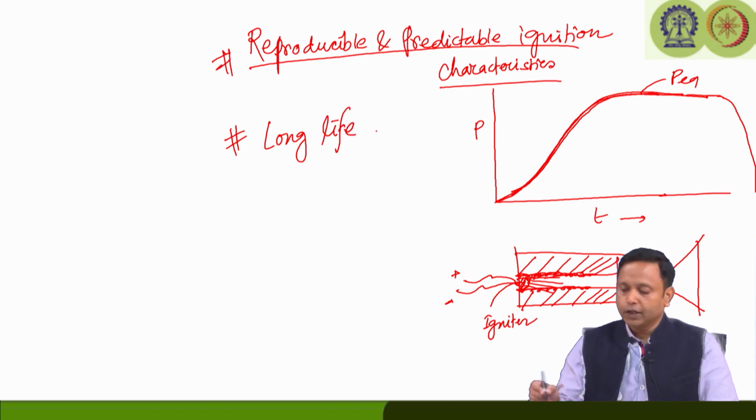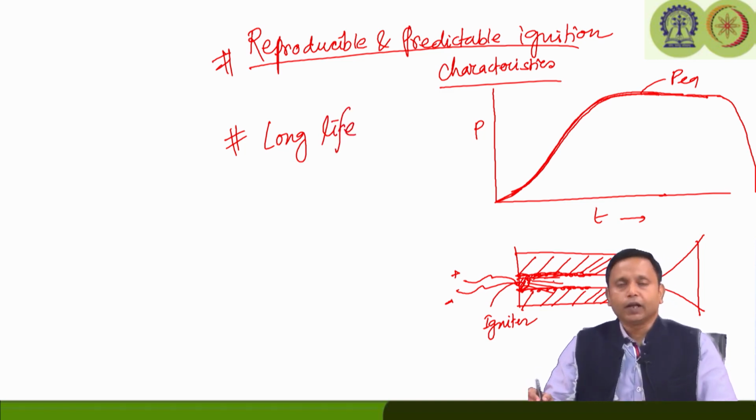So, let us say we made the grain, for example, a cartridge loaded grain. We know that it is a freestanding grain, the grains are made separately, they are cast and cured separately, and whenever required they are loaded into the rocket motor. So, let us say for missile applications, it is not always necessary that we make the grain and immediately use it.